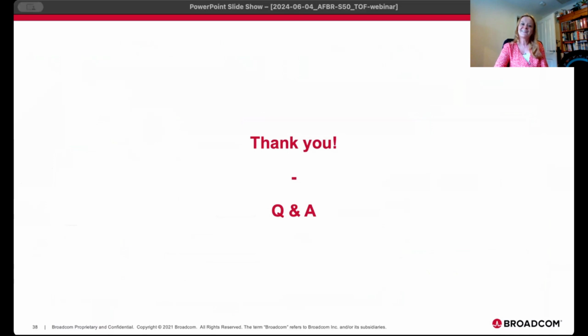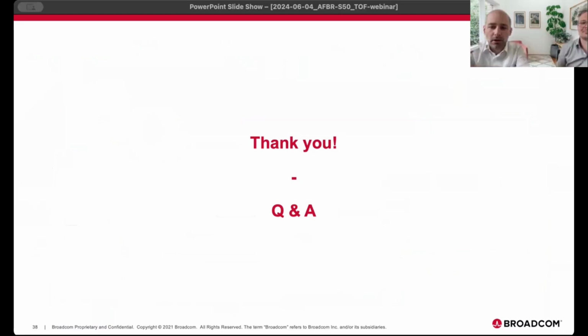Yeah, so actually we're working, as mentioned in the beginning, with a 32 pixel array. So we have 4 × 8 APD pixels. This is the resolution for each sensor. And we have for all our variants a pixel field of view which is 1.55 degrees times 1.55 degrees. So this is the resolution you can achieve. But I also would like to add that our sensitivity is so good that if the object is smaller than this field of view, in most cases you're still able to detect the distance to the object.